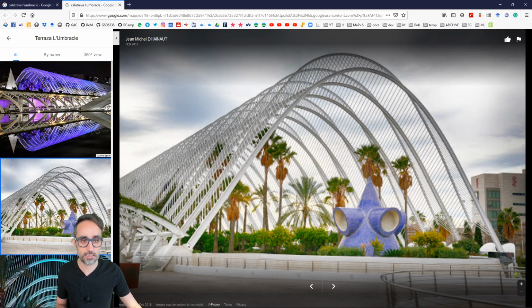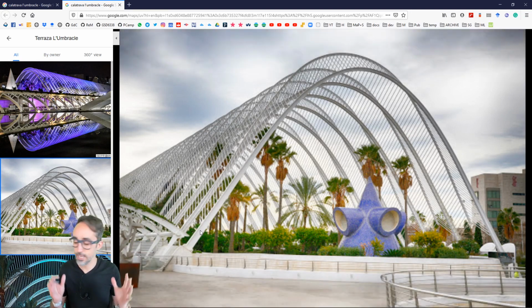this beam as well. And something that is interesting is that the profile of this beam has a depth here that is larger than the depth here. So as the beam goes up, it becomes thinner and thinner, which I guess makes sense because structurally it probably has less stress on the top than at the bottom. So that's something that we also want to model in our exercise. So how about we go to the whiteboard and do some sketching about what are the parameters that we want to control here, and then we start implementing this.